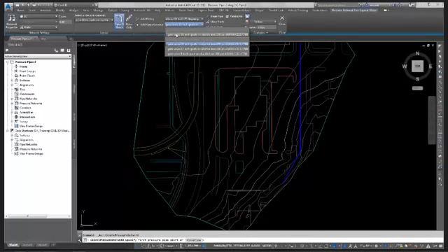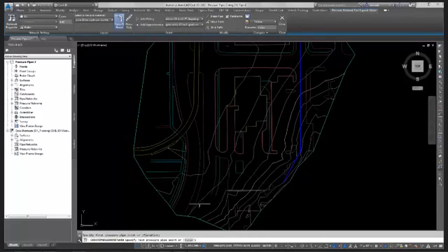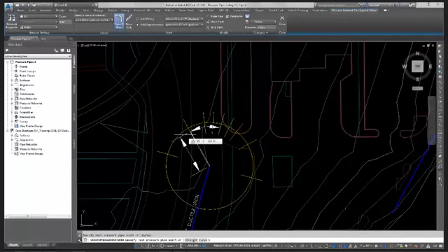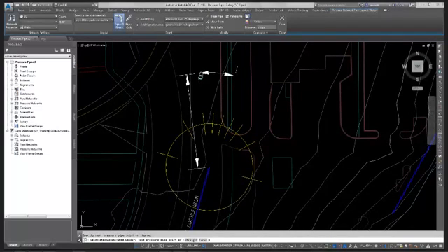I have those sizes. The best part about this is when I build my pipe network, when I click and put my second one in, I get my compass, and it automatically builds the compass based on my parts list. So if I don't have any 90-degree elbows, I don't get the compass for 90 degrees. But I can come in and put one there, and then maybe we'll keep just jogging up my line.